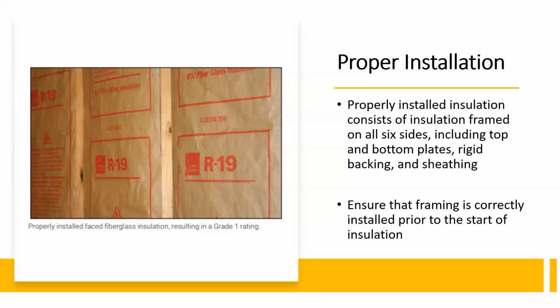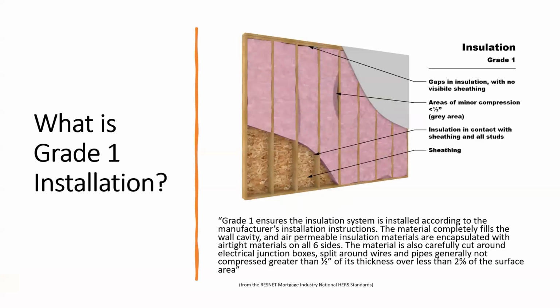We saw that on prior webinars. You've got to actually determine where the thermal envelope is, and that all 6 sides of that insulation is in contact with what is considered the air barrier. Period. If it's not in any one of those 6 sides, it's a misalignment of the air barrier and thermal boundary. Period. Needs to be more in contact.